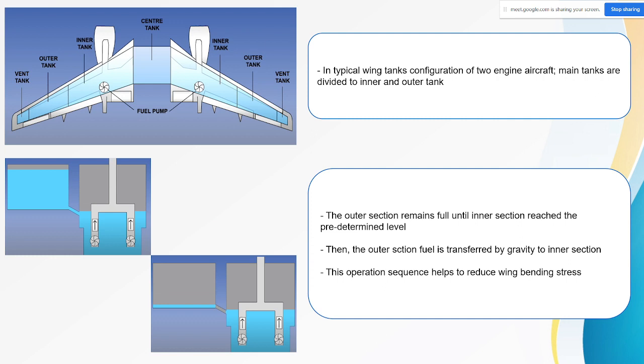So that means the scavenge jet pump will just pump the fuel to the wings, so it doesn't matter where it goes. Yes, the scavenge jet pump is installed in tank number 1. It is connected to the center tank. When the center tank is consumed, it is not necessarily completely empty, so it pumps the remaining fuel into fuel tank number 1. So if it pumps the fuel to the first tank, won't it create an imbalance there?